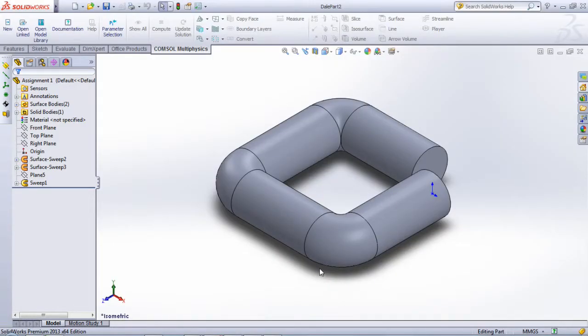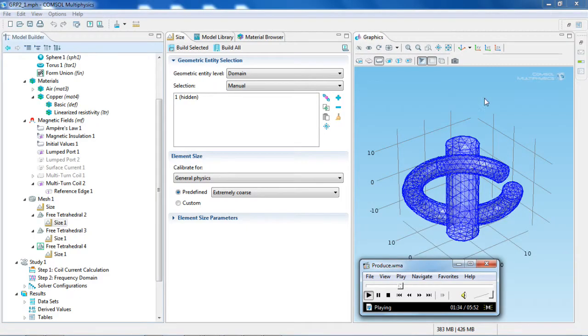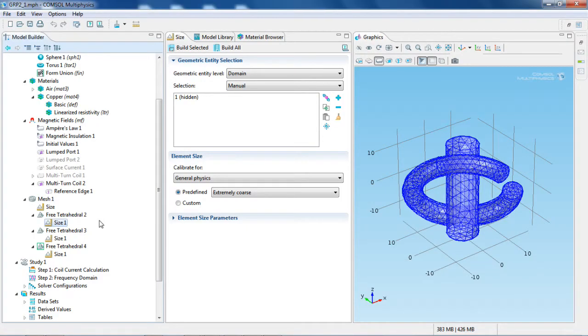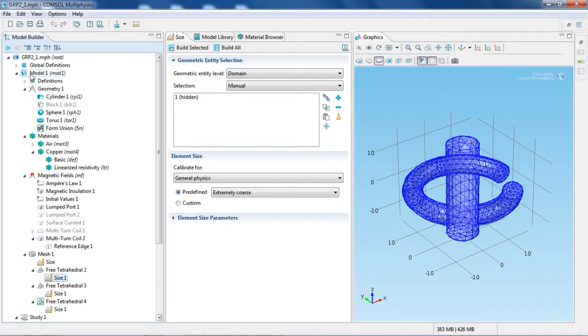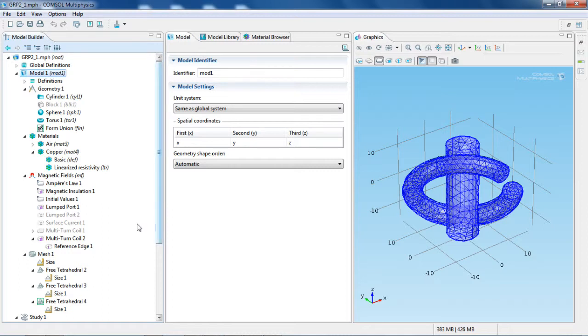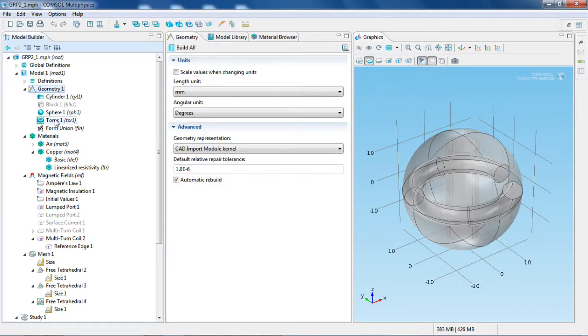Two different types of Rogowski coil were investigated: a circular Rogowski coil and a diamond-shaped Rogowski coil. The magnitudes of the voltages induced in both types of coils were investigated when a current-carrying conductor was threaded through the Rogowski coil's loop. The first simulation is shown here.